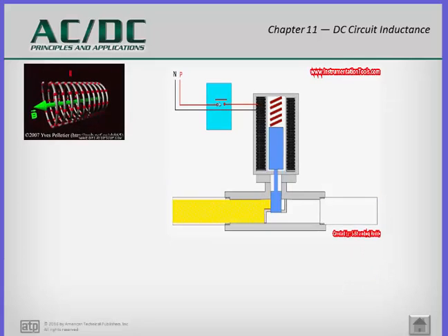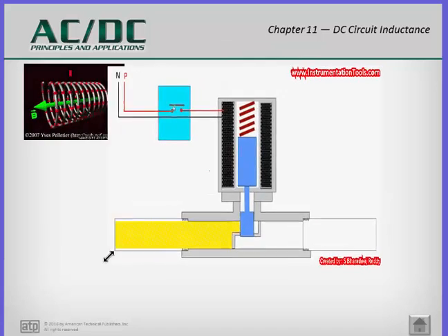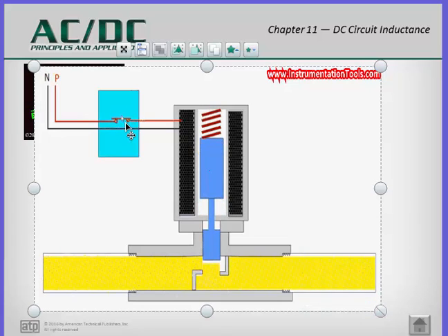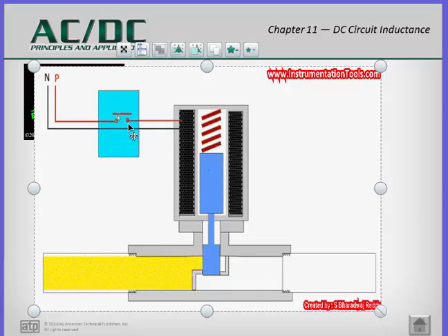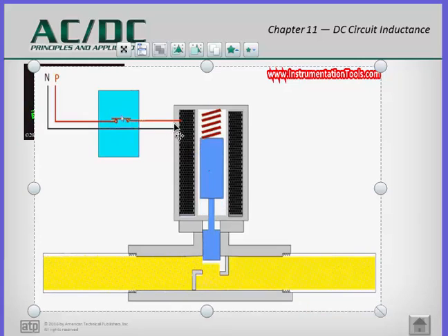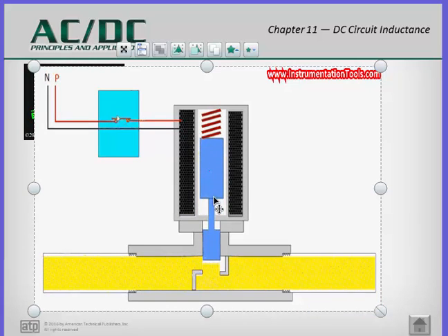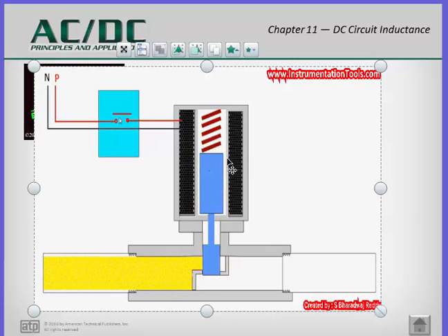Now let's see one in circuit or in process. Here we see where you have a DC current, and a solenoid is only going to work with DC, just like a relay is only going to work with DC. When this is closed, with both of these contacts being connected, it sends an electrical signal through this magnetic field, and that will draw up this plunger made of metal.